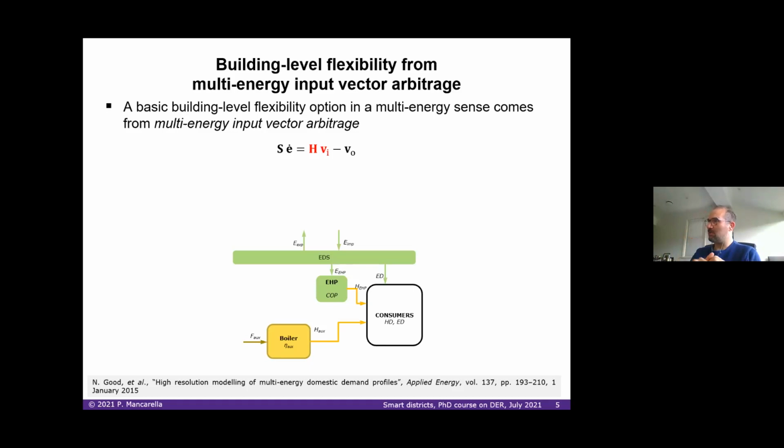However, when it's really cold in winter, with temperatures in degrees Celsius negative, even very negative, you go to Scotland, a place like -10, even -15, basically heat pump performance is very, very poor. I'm talking about air source heat pumps. Ground source has other issues: there's not enough space to put ground source heat pumps, especially in urban areas. So an air source heat pump at -5, -10 performs very, very poorly, especially compared to resistive heating.